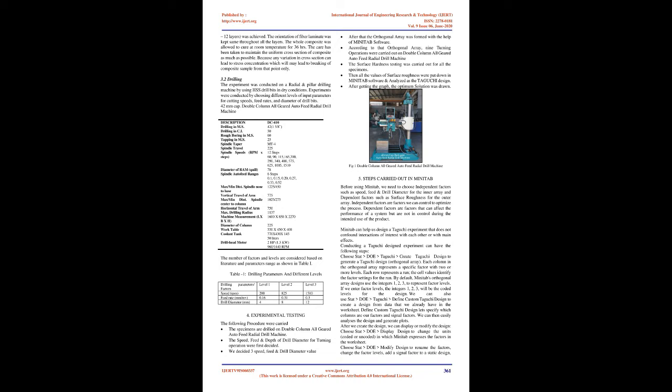The whole composite was allowed to cure at room temperature for 36 hours. Care has been taken to maintain the uniform cross-section of the composite as much as possible, because any variation in cross-section can lead to stress concentration, which may lead to breaking of the composite sample from that